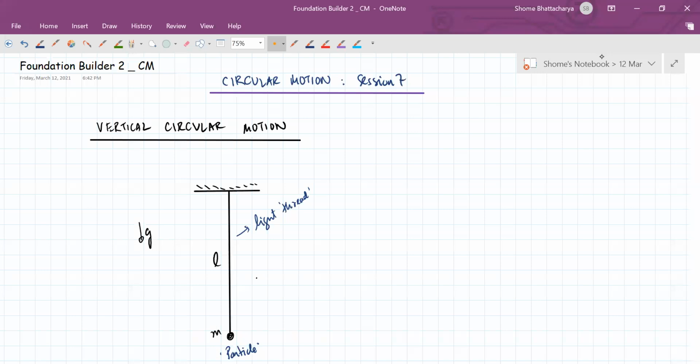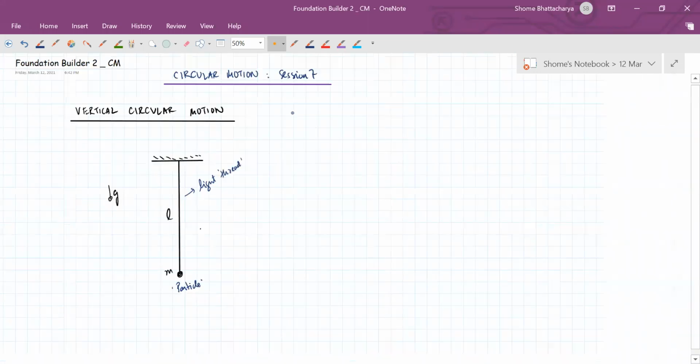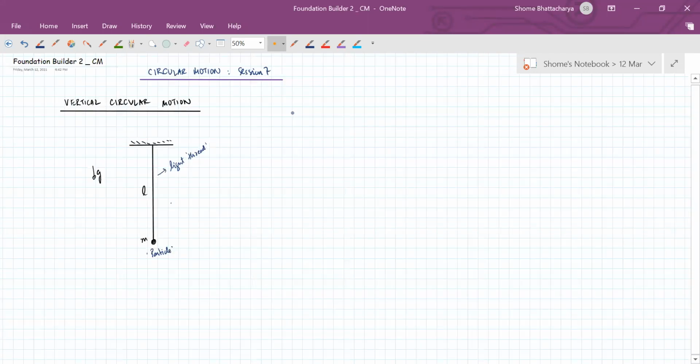yes, Bhargav, that is correct, that is the maximum speed that is safe to drive on a section of the highway which is curved. The maximum speed that is safe such that there will be no slipping is determined by the banking angle concept along with the coefficient of friction. And of course, in real life engineering systems, the maximum velocity or any such limiting value is always given such that there is quite a bit of margin. So if the specified maximum velocity is a certain value, then the slipping will actually start occurring at a velocity even larger than that maximum value.